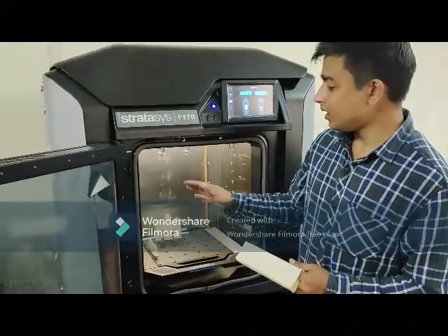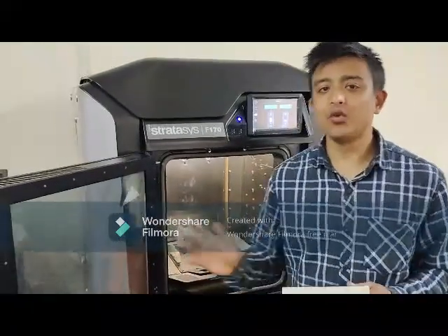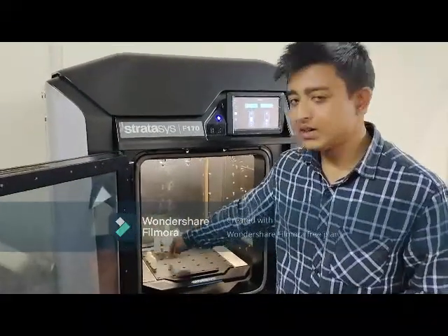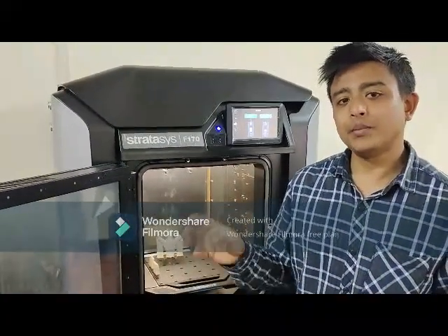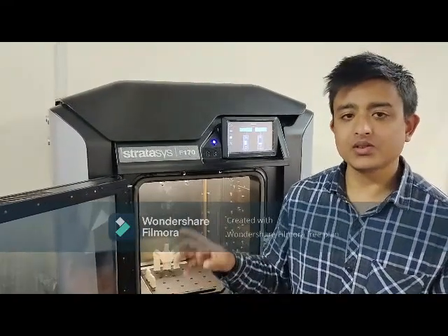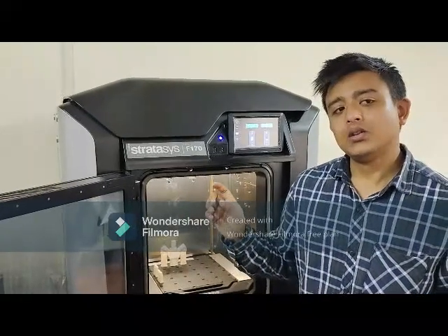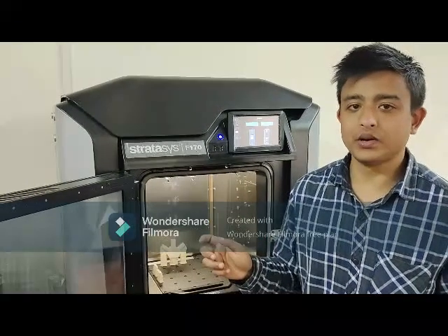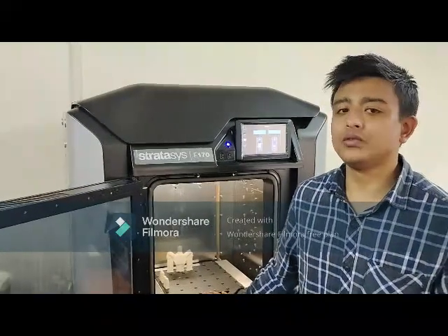Second thing, suppose the temperature goes down, like in Shillong in winter time we have 5 degree, 4 degree temperature here. Because of temperature drop, it is printing one layer, second layer, fourth layer. After the completion of fourth layer, in the fifth layer the temperature may go down, maybe by 5 degree, 6 degree, the temperature of the nozzle head, the heater in the nozzle. So there, when the temperature goes down, obviously the thermoplastic won't be melted properly, and we will have some effect on the printing part. So also it is taking care of that thing.